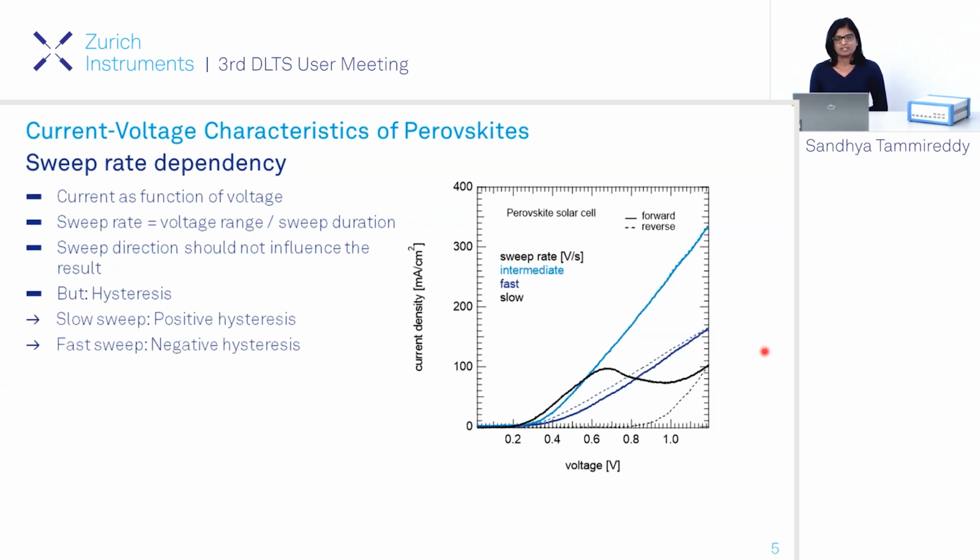Here you see an entirely different response in comparison to the last 2 measurements. You observe a huge amount of hysteresis in your IV curves. Interestingly, in this case, the forward current doesn't show a clear exponential behavior at all, and it contains higher current values compared to the reverse case.